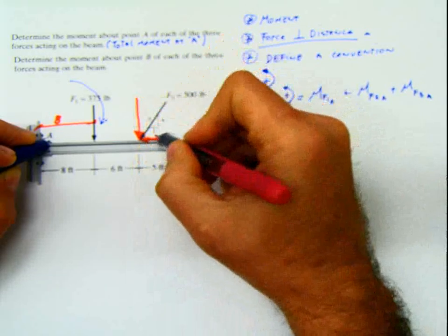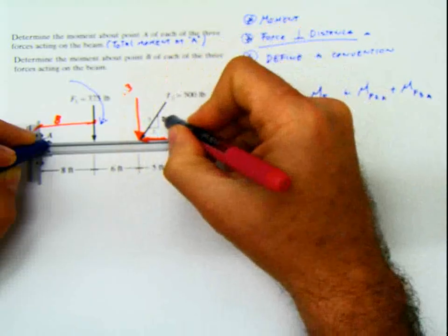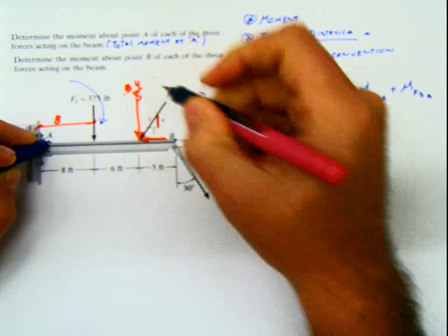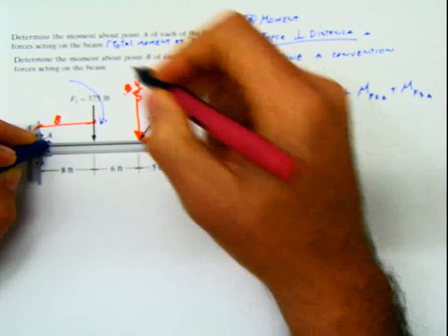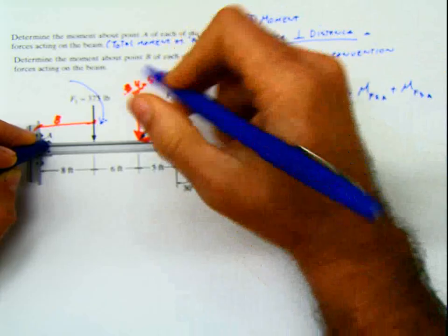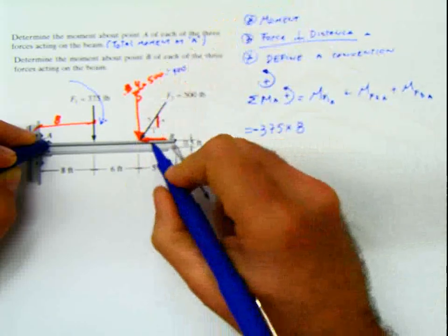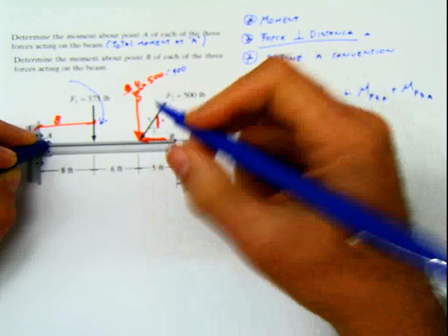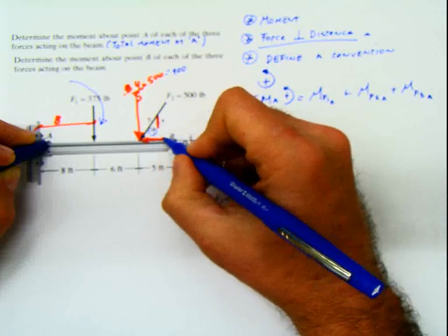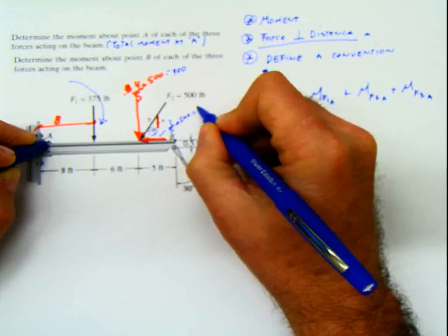The vertical component is going to be 4/5, because it's the vertical, this one. 4/5 multiplied by 500, which gives us a vertical component of 400 for that force. And the horizontal component, I'm going to calculate it even if I don't need it later. It's going to be 3/5 times 500, which makes 300.